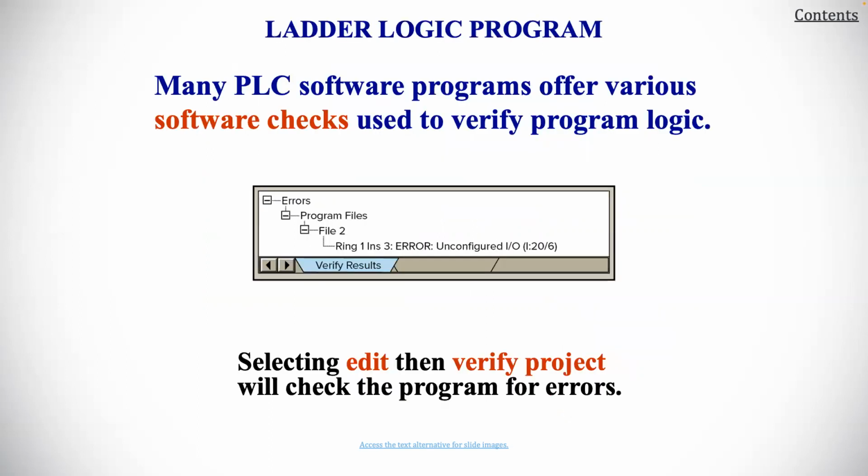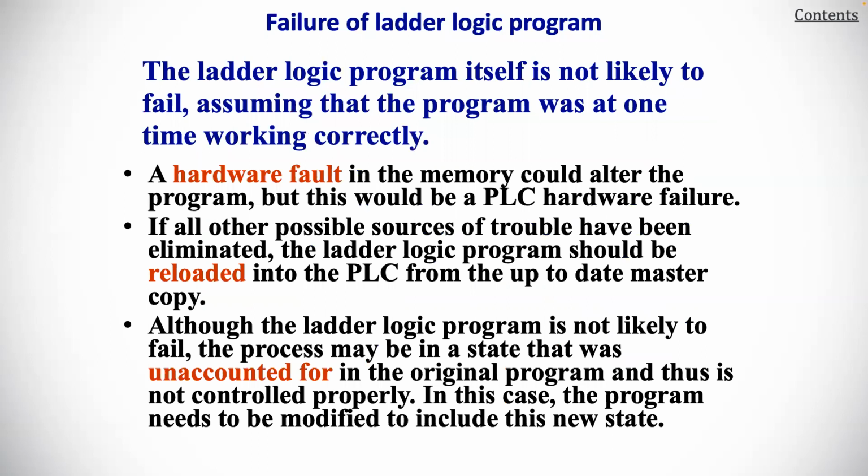Many PLC software programs offer various software checks used to verify program logic. So you can select edit and then verify project, which will check the program for errors. That's a good thing to do before you upload it and try to see if it's operational. The ladder logic program itself is not likely to fail, assuming that the program was at one time working correctly. You can have a hardware failure, and the memory could alter the program, but that would be a PLC hardware failure.